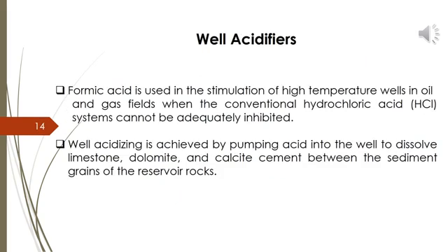Formic acid is used in the stimulation of high temperature wells in oil and gas fields where the conventional hydrochloric acid systems cannot be adequately inhibited.